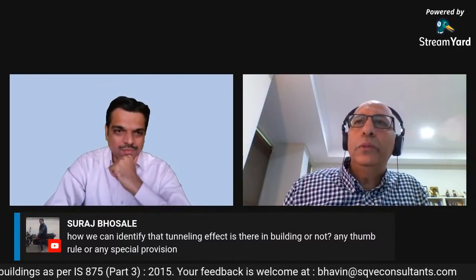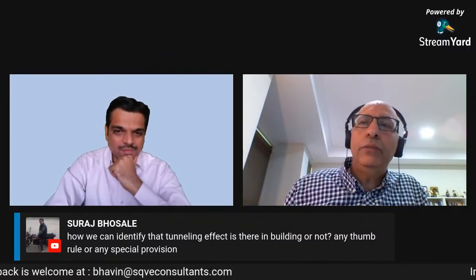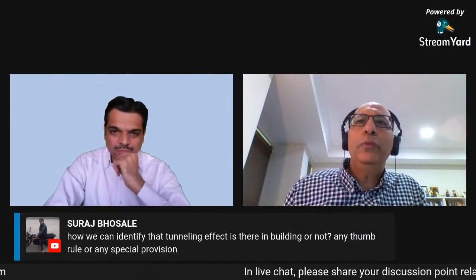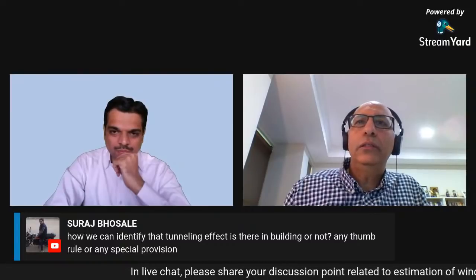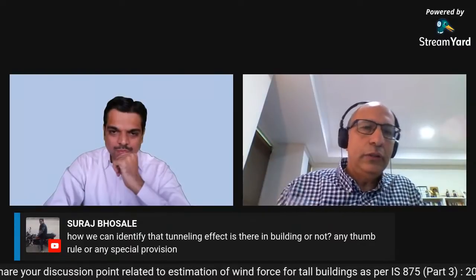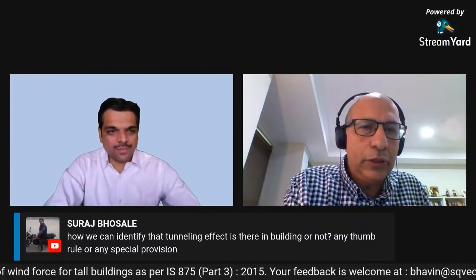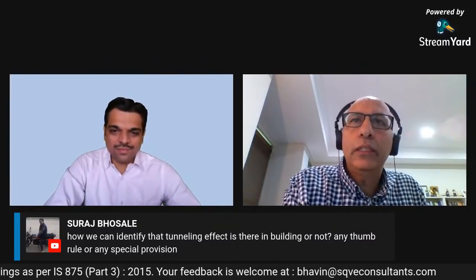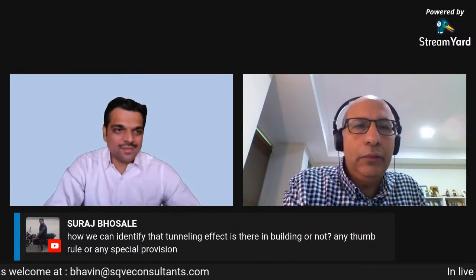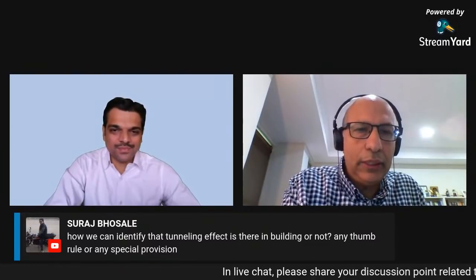The general rule is sound, although, as I mentioned before, be careful if you find that the crosswind is governing. This 1.35 factor should increase to at least 1.5. And in any case, you should consult a wind tunnel laboratory such as WindTech Consultants. If you're finding that the crosswind is governing, that's an indication that this building is sufficiently dynamic to warrant a more detailed study.